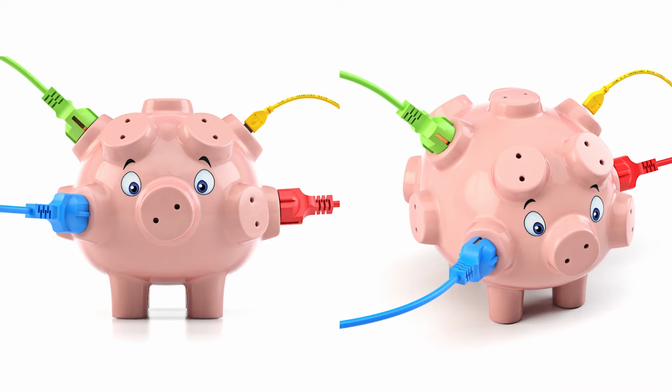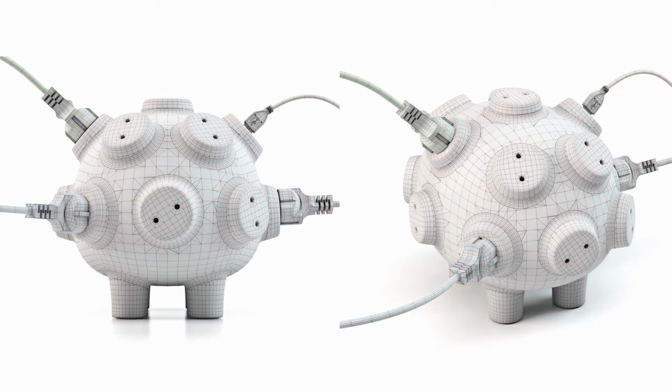And as you see, this has a lot of fillets and holes that will be really tricky to model if you use normal subdivision modeling. So by blending with Meshfusion, I can design this a lot quicker and still have a procedural model that I can change on the fly.